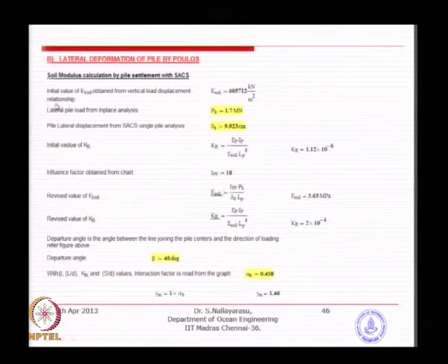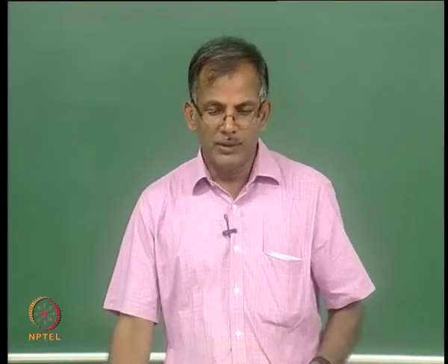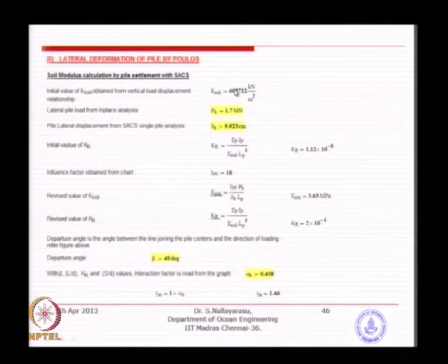So, you see here the initial value of soil modulus for a multi-layered soil is given to you, in case of examination or in case of your practice. This value is given based on computer analysis, because it is a multi-layered soil. The analysis has been done separately, and then you have the initial value obtained from the load displacement graph. Otherwise, you have to establish this.